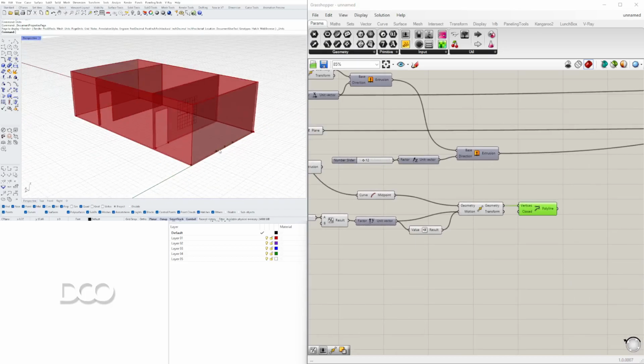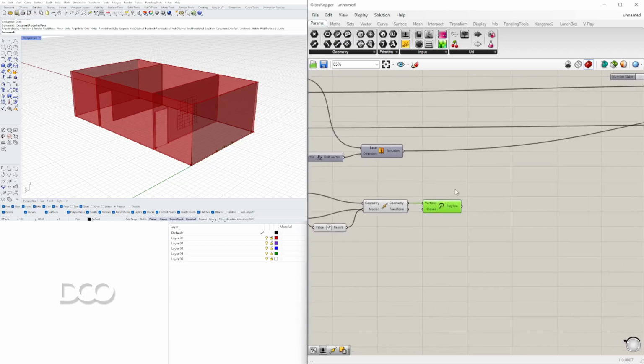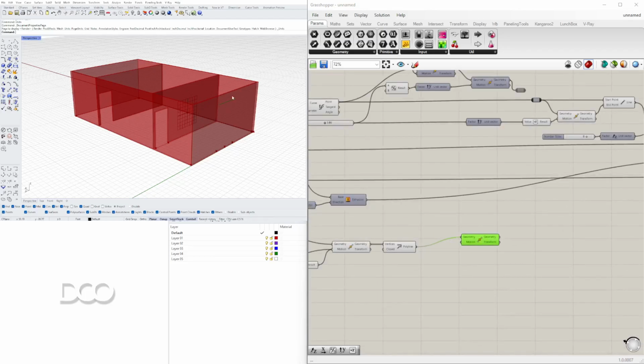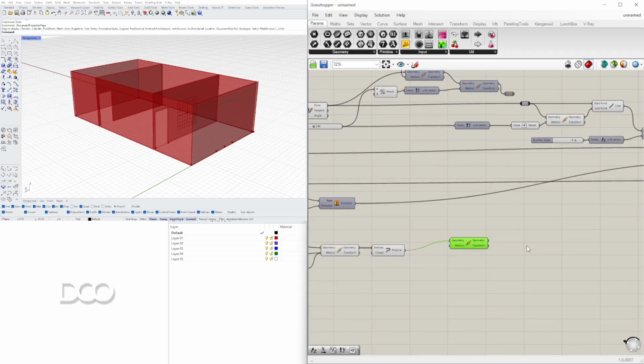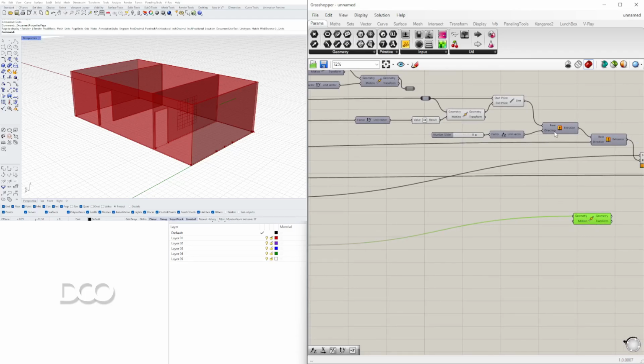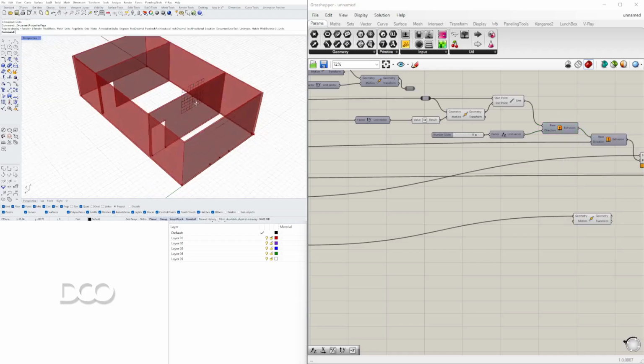Next, we'll take this line and move it up to the head height. This is going to be a little different than the door, because we want to move this up to the same location as the door head. It's not necessary, because sometimes you will have window heads at different locations, but we already have that, so we can always change it if we want to. So it's at 8 here. That's how big the opening is.